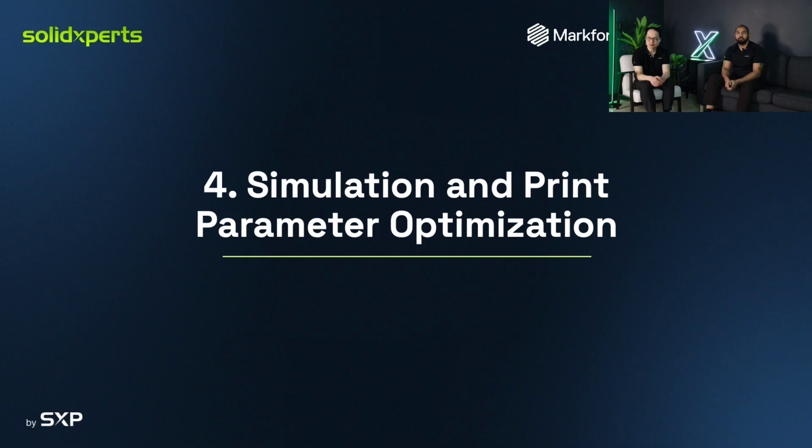go to the Simulation tab. We'll obviously validate that we still have the same safety factor we saw earlier. And now we're going to use an option called Optimization. This option will calculate different print parameters, different infill settings, as I mentioned, fiber placement, and so on. And it will give us results.